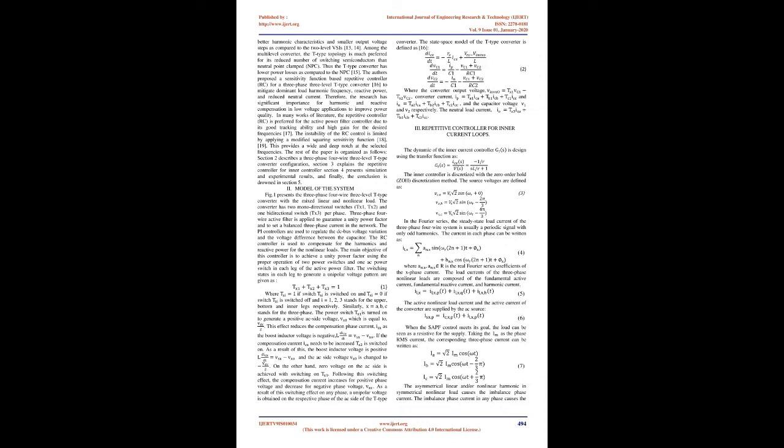The harmonic effects on the phase line increase harmonic distortion and power losses. Similarly, harmonics increase the circulation of zero-sequence harmonic current on the neutral line and delta winding of the distribution transformer. The neutral current depends upon the type and condition of the load in the system. In many cases, the neutral line current exceeds the phase line current.